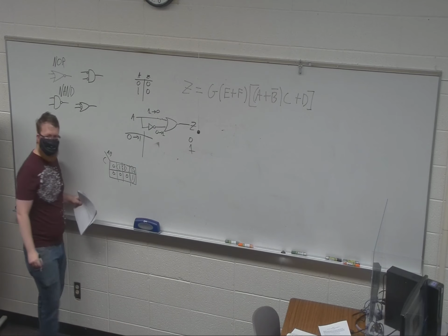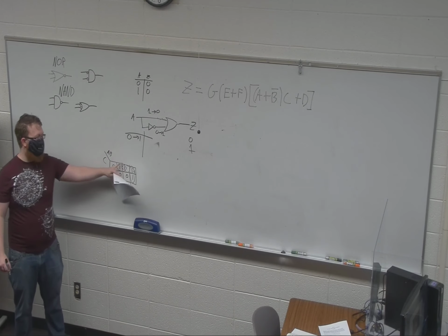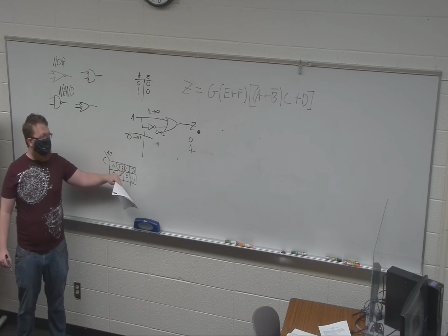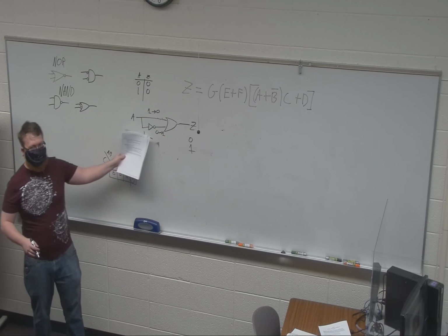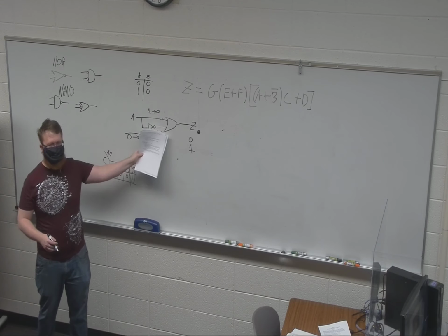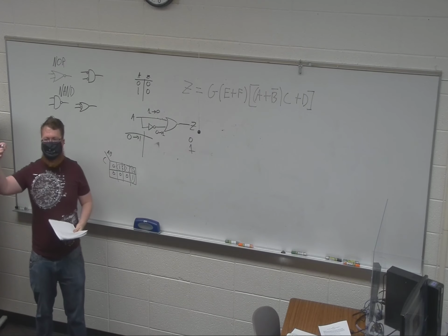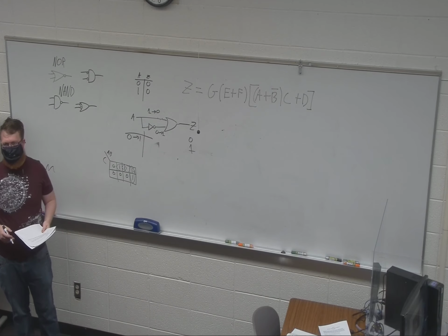So now they're joined together. That doesn't change the OR, it's just one more OR term. And what that OR term is doing is adding another path for the data to flow through when it hits this OR gate that won't cause a glitch. So it's adding complexity to the circuit in order to prevent these static errors.